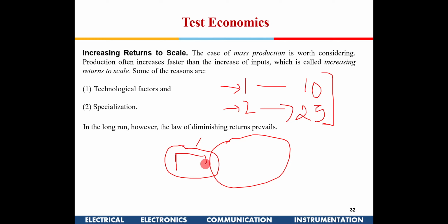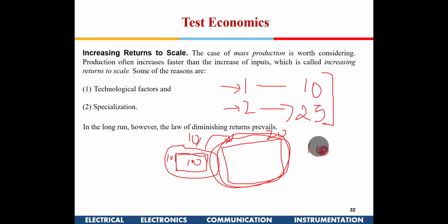Okay, so this is a wafer, say of 10 inch. This is a 20 inch. In the 10 inch, I might have 100 dies, and 10 dies in the corner are getting wasted. Now I have increased my input, I have doubled it, I have taken a 20-inch wafer. In the 20-inch wafer, it is possible that only at the edges, only 10 dies are faulty, and instead of getting 200 I might get 300, because the faults might be only in the outside ring.